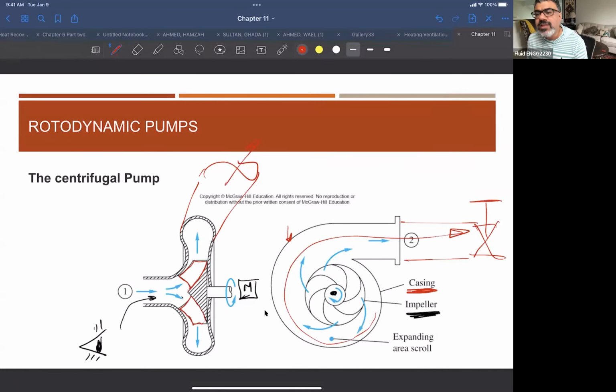Okay. So what happens if this valve is totally closed? What will happen here? Anyone? Remember, for the piston pushing all the fluid, the clearance is very tight, so the liquid has to move out. That's why we call it positive displacement.